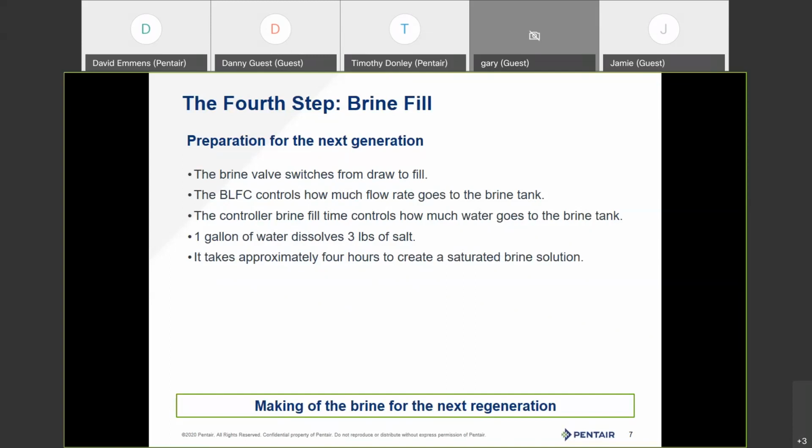Okay, and in a traditional brine tank situation, we don't have to worry about the additional volume created by salt. If you're dealing with a brine tower or separate source regeneration with separate source brine solutions, that's going to be a little bit different scenario because that situation isn't controlled by the float.